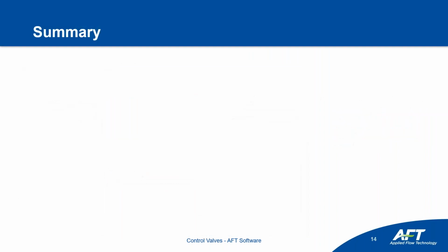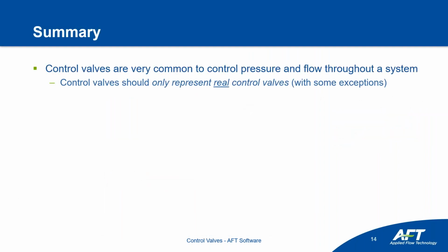So that's everything I have today. Let's review what we have. Again, control valves are very common. We looked at all those applications at the start. And as a rule of thumb, control valves should only represent real control valves you would have in your physical system. Obviously, there are some exceptions.